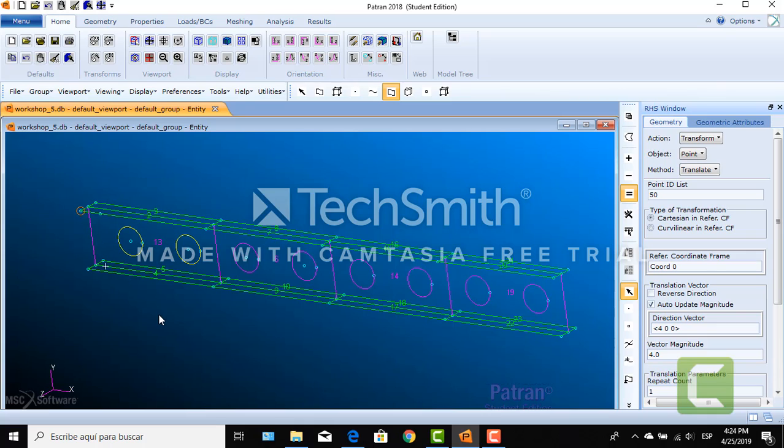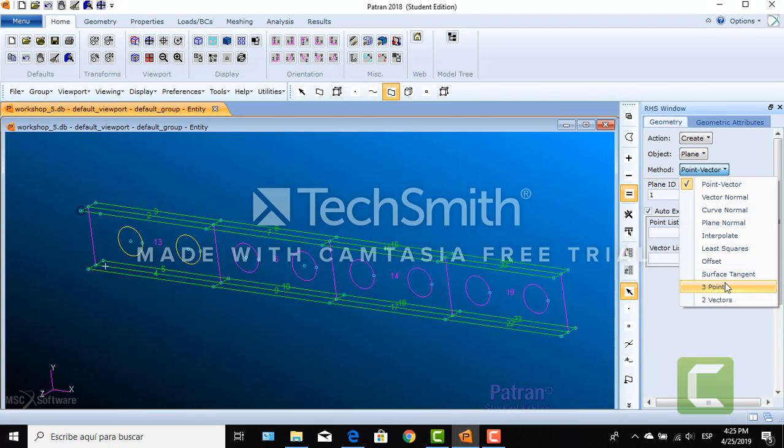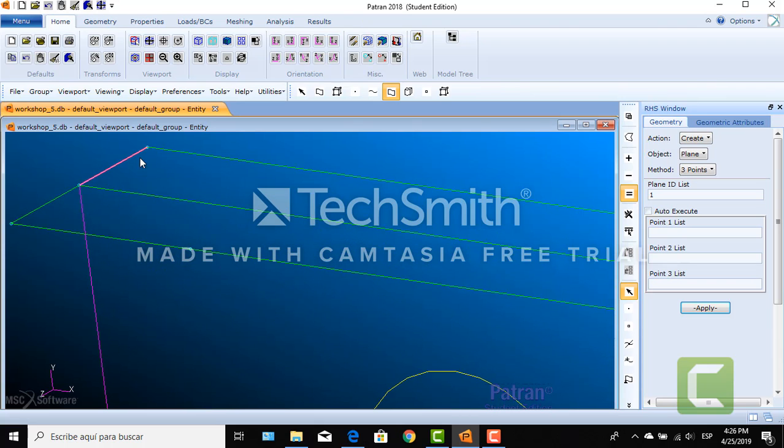And now we're gonna create another plane using this point as a reference. So we click on action, create, and the object, as I told you, is going to be a plane. The method we're gonna be using is the 3 points method. In order for us to create that plane on 3 points, we have to turn off auto execute, and we're gonna zoom in to this part.